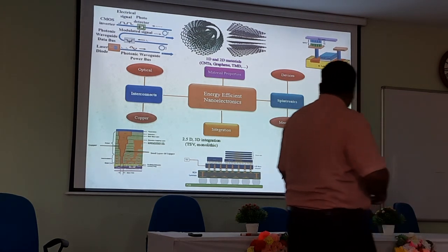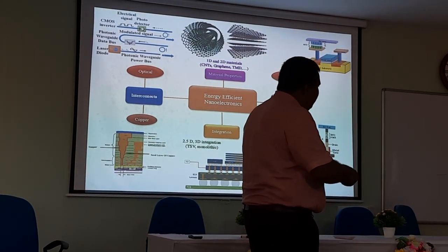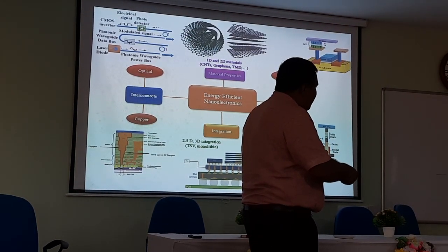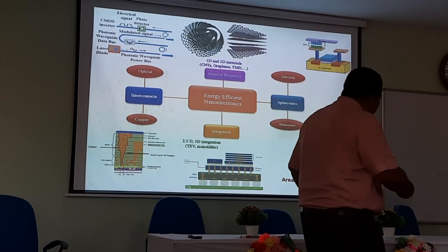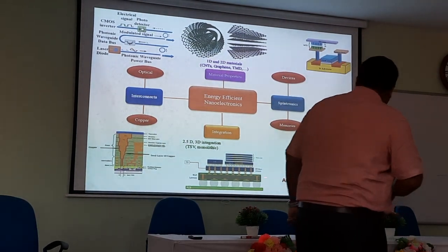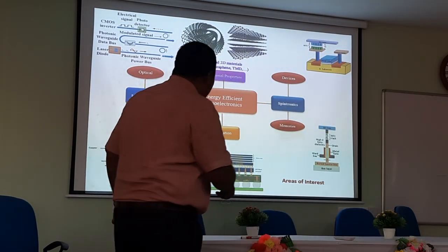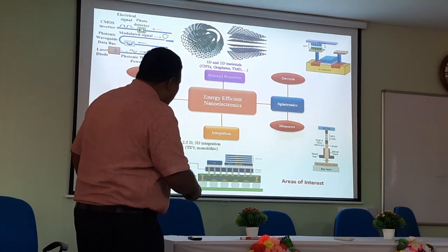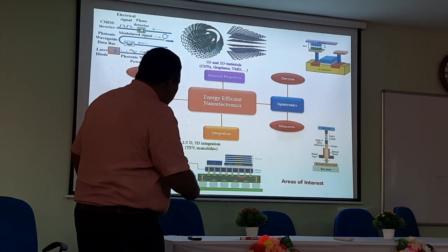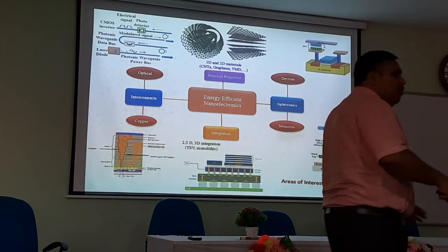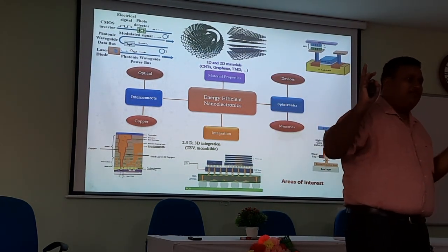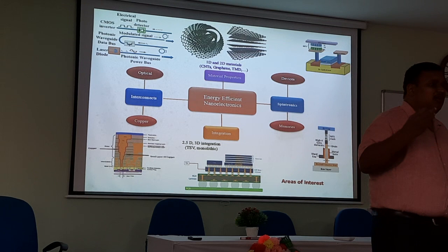2.5D is wherein you have multi-chip modules. Just think about all these chips connected through interconnects in the same domain, or sometimes beneath that. This is what we call the interposer. This is 2.5D silicon which we are talking about, and this is where you keep on connecting. So it's not 3D, and 2.5D, all kinds of things people have explored and are working on a lot.